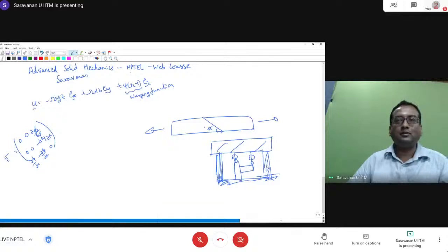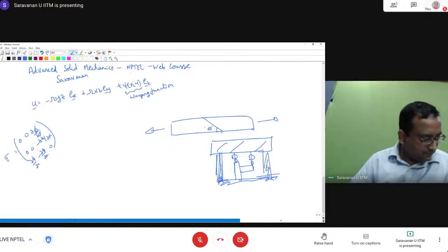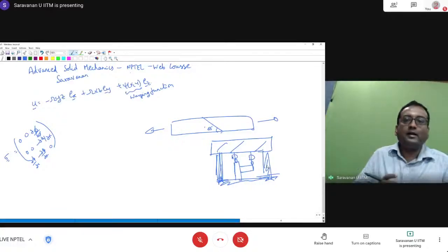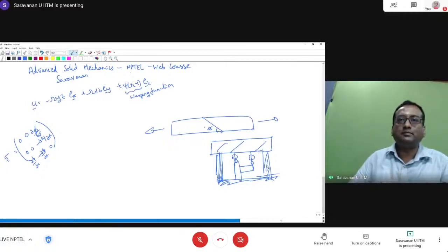Okay, so you can't make a problem much simpler than what it is, or more complicated than what it is required to be. So you apply beam theory on cases where you don't satisfy all the assumptions also. But there are certain assumptions like homogeneity. If you have multiple materials connected together, there you have to make sure the assumptions are satisfied.